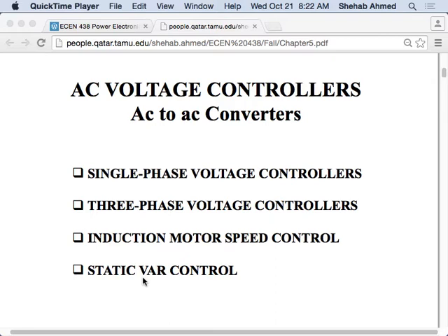So that's the static VAR controller, and we will talk more about that. Induction motors are very similar. If you took 338, for example, or even if you hadn't, induction motors are basically like a transformer, right? So it's like a rotating transformer from an equivalent circuit perspective.